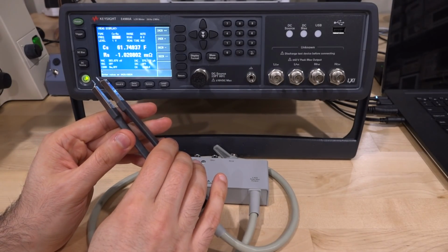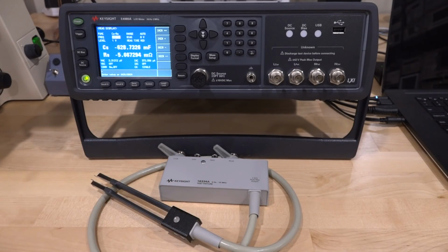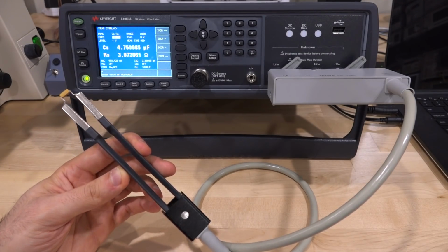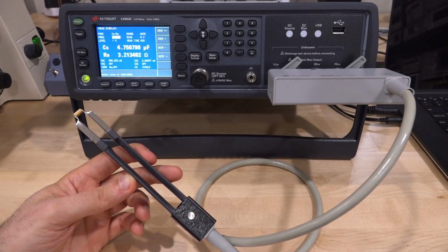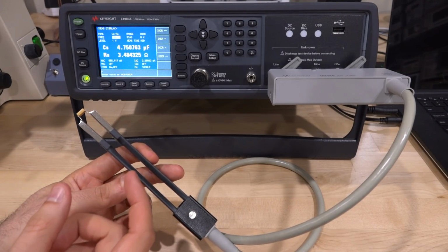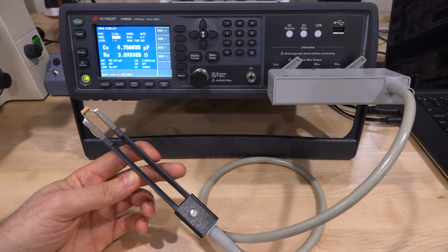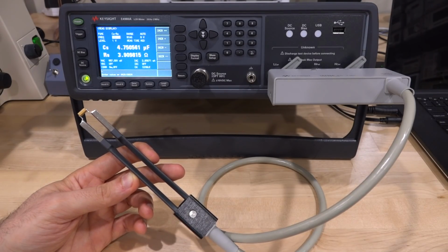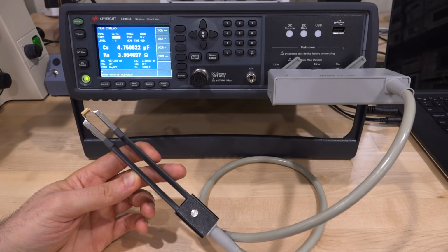So for a different model of this that can go to higher frequency, it can still be used. And this tweezer allows you to measure surface mount components, of course. So we can measure something really basic with this. Here is a 4.7 microfarad tantalum. You can see it's being held by the tweezers and no problem in the measurement at all. You can measure things of different sizes, of course, because there's a certain displacement between the two leads. You can buy a model which comes closer or further apart. I really like this one, especially when you don't know what it is that you're measuring at all, and you can switch between inductor and capacitor to find out what it is.